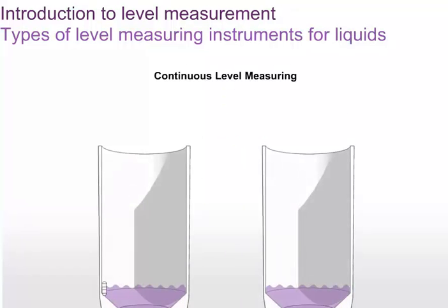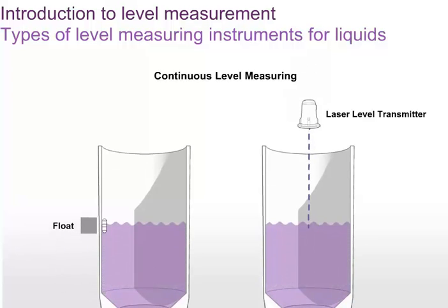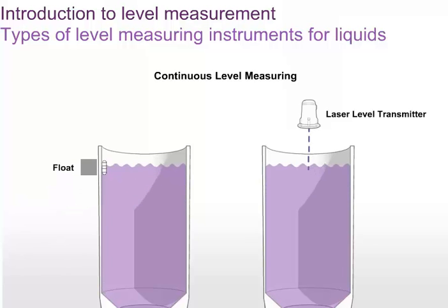When dealing with liquids, the use of a non-contact type of level measuring instrument provides a more reliable reading and avoids problems of contamination. This is especially important if the material being measured could cause damage if it came into contact with the instrument. Contact type instruments can corrode when in contact with certain liquids. Extremely viscous liquids are very difficult to measure with a contact type level measurement instrument.